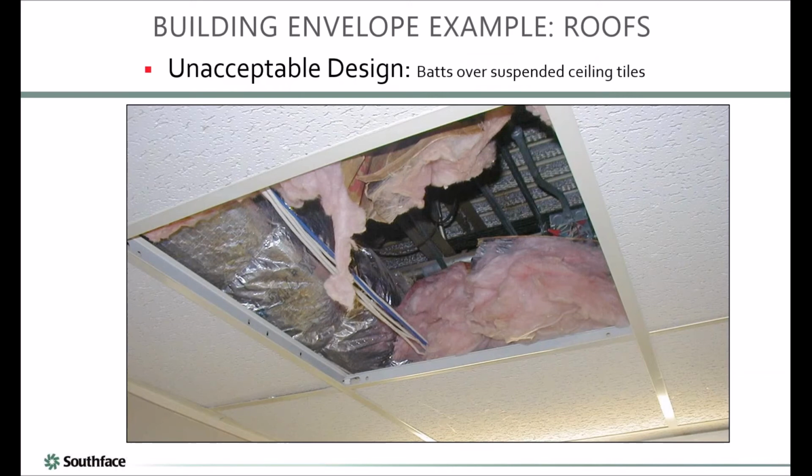A lot of times the fiberglass particles become more airborne over time, and that's an air quality concern. Even if this was done correctly, which it can't be, it often gets moved around. And it's not airtight. You've got 8 feet of crack for every one of these single drop ceiling tiles, and ventilated light fixtures and so on. It doesn't meet the definition of thermal envelope.